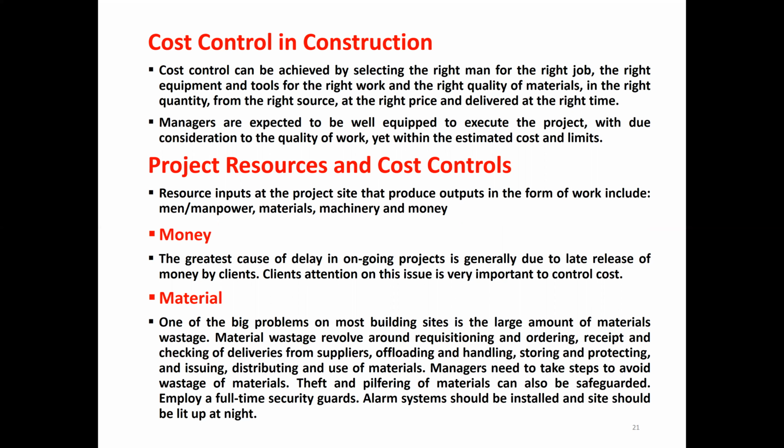Theft and pilfering of material can also be safeguarded. We should employ a full-time security guard. An alarm system should be installed, and the site should be lit up at night. So there should be proper lighting, not dark at the site, and there should be an alarm system in the storage, so that no one touches it at night time. We have to put a security guard so that material is not stolen.